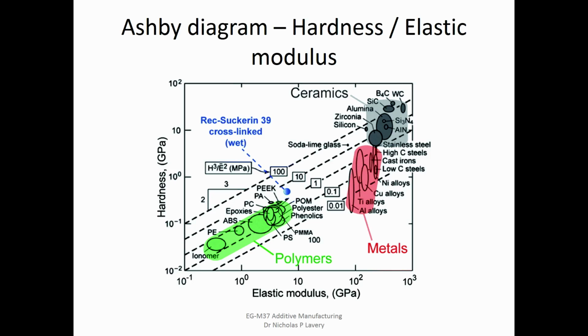And they published this paper in Nature saying how it was possible with a material like 316 that they worked with to overcome the traditional trade-off between tensile strength and elongation. So often you can get very high tensile strength at the expense of elongation in the material. And they were saying that additive gives you the possibility to engineer the microstructure of the material because the laser is so small.